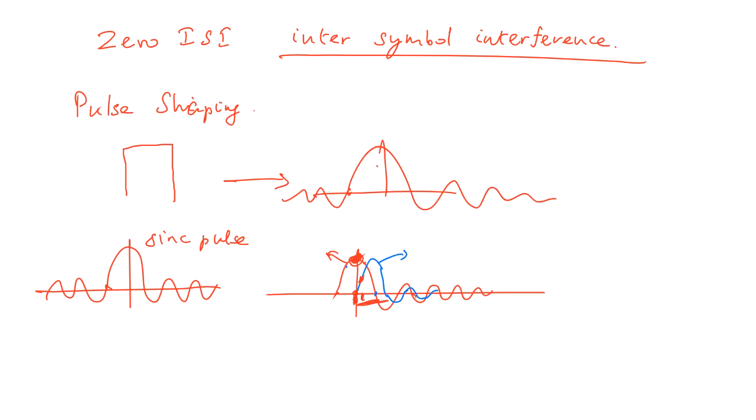Okay, distortionless, of course, yes. When we say zero ISI, that means the symbols are not distorting each other. There may be other forms of distortion by noise or other factors, but the symbols are not affecting each other. For that, we need to implement our receiver correctly. The sampling has to be exact, synchronized and perfectly aligned.